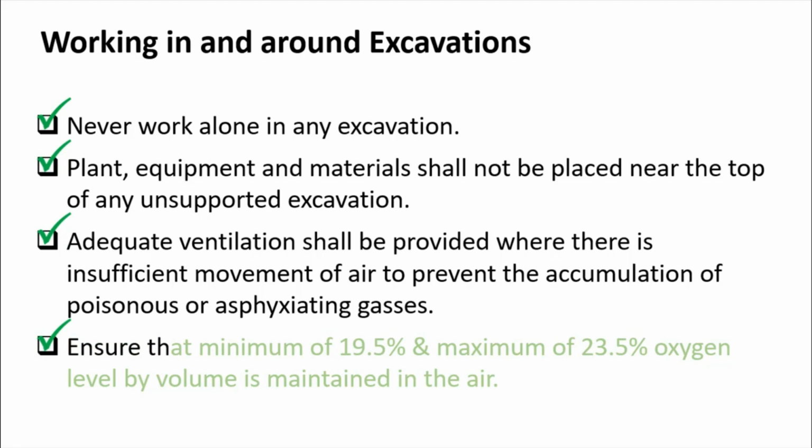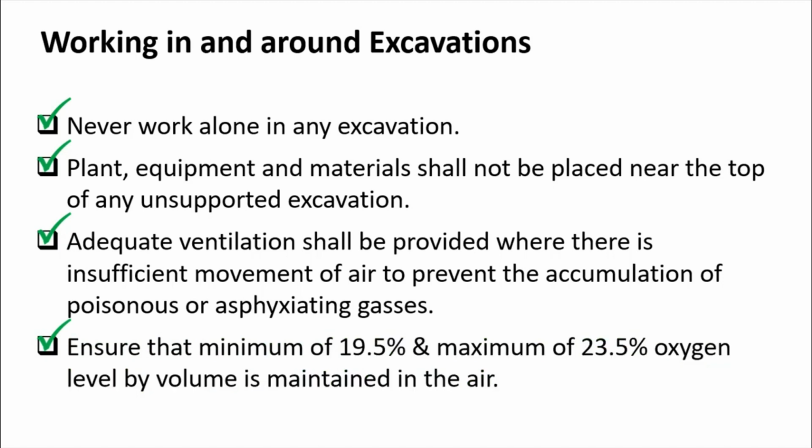Ensure that a minimum of 19.5% and a maximum of 23.5% oxygen level by volume is maintained in the air. So how are we going to check this? Of course, you have the gas detector. Commonly in the construction site, we use a multi-gas detector.